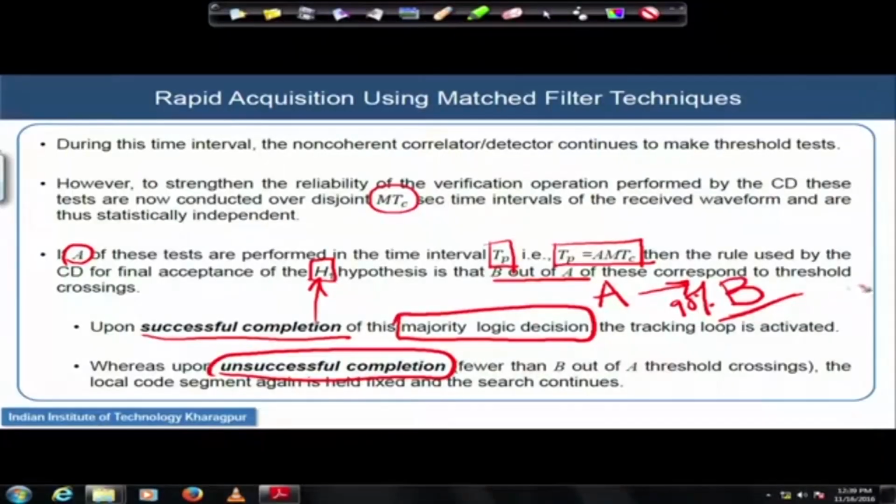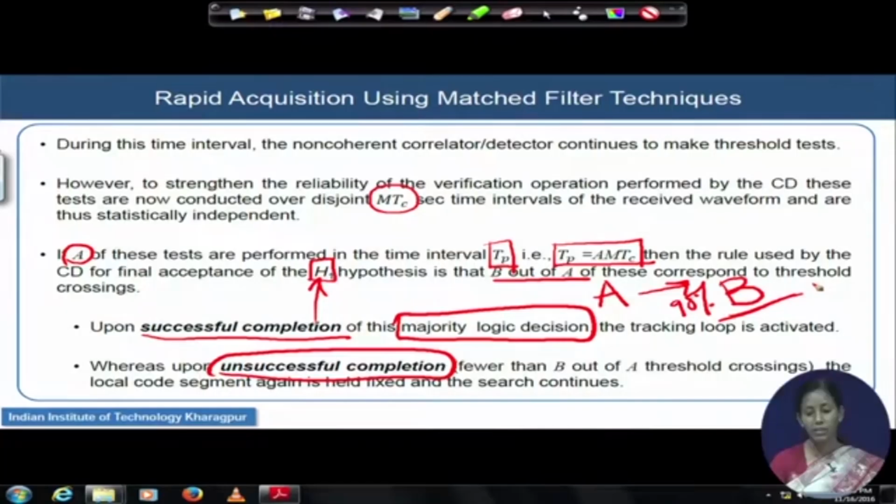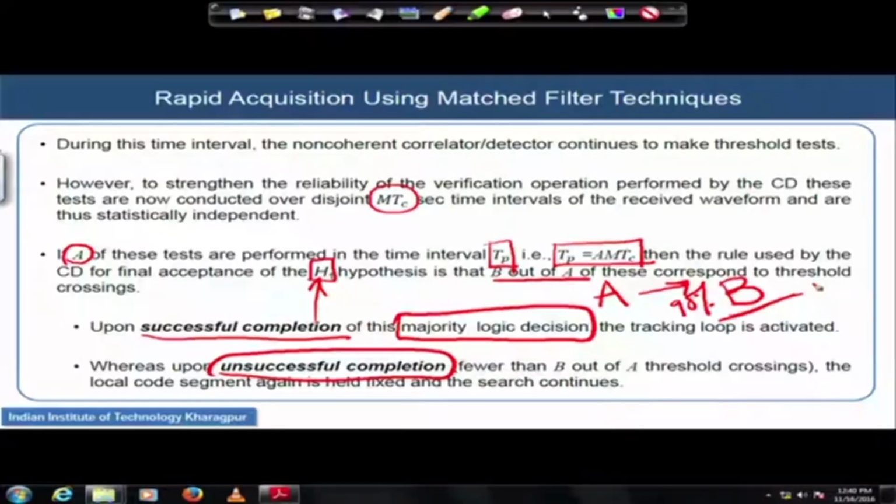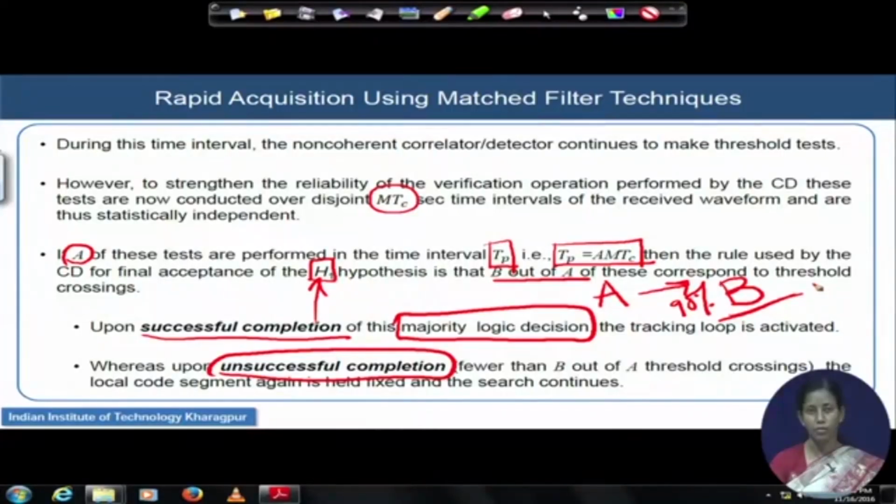So, there is a compromise, a crucial decision you have to take as a system engineer: how good the synchronizer should be and how much time I have in my hand. How strict should I be in taking the decision, how much time should I let elapse, and what final error level of the detected bits am I happy with. It is the level of quality of service in terms of the bit error rate that is predefined from the customer point and from a design point, and that will lead back to selecting the value of the capital B inside your decision device.